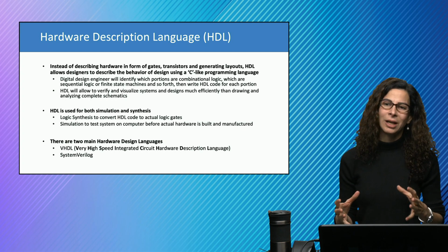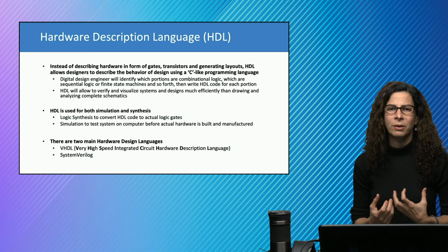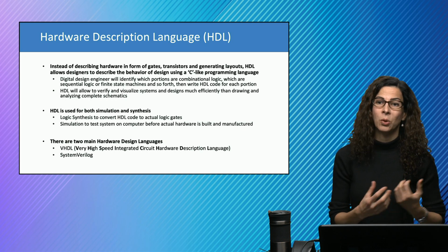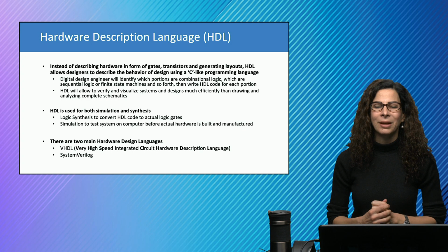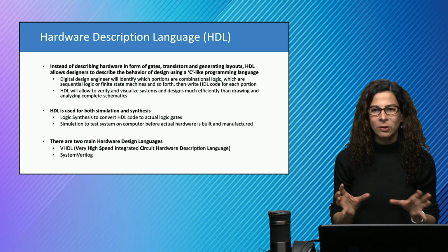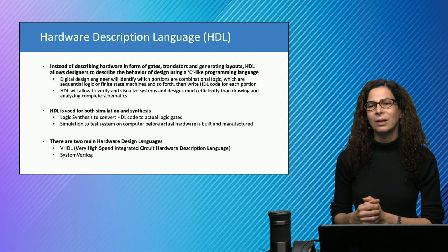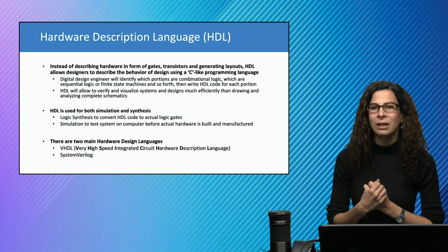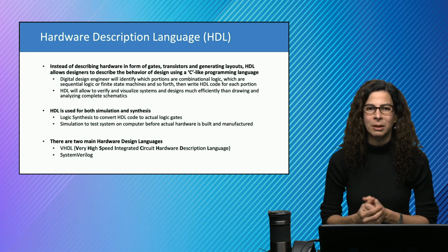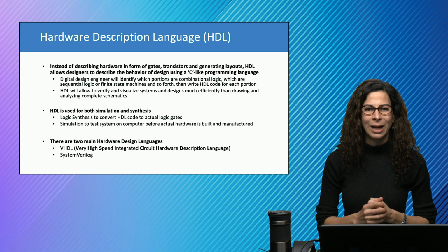The task of the digital designer after creating this type of language then would be to determine which part of the code will be sequential, which uses parts of the memory, and which parts will be combinational, which we'll be going into details in the next set. But the nice thing is these tools would actually take this description, make a high-level circuit, and go through the compilation of this into a piece of hardware, which is called the synthesis process. And not just that, the HDLs also enable us to test and verify these circuits that we've written in these programming languages. In short, we can use an HDL for both simulation and synthesis.